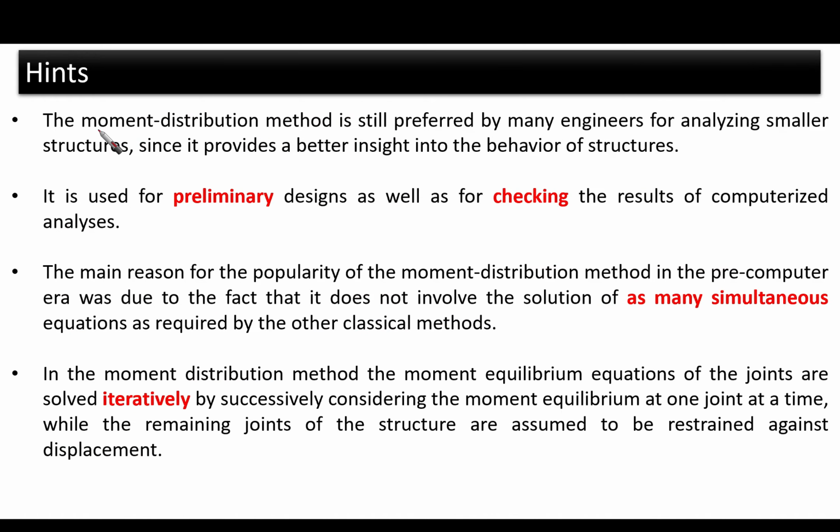Something important also is that the moment distribution is still preferred by many engineers for analyzing smaller structures. So if you are facing a smaller structure, moment distribution is going to be the best for you, because it will be quicker and easy to implement, since it provides better insight into the behavior of the structure.